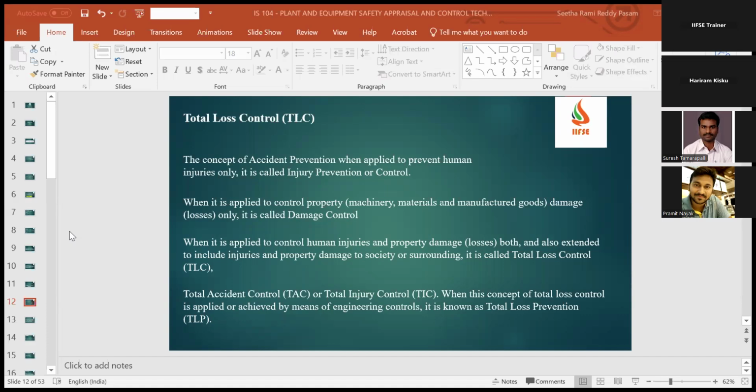then I'll go for engineering controls. I can put sensors in case of any leakage, detection systems, and auto controls. I can even automate the process, with no human intervention in my process, completely a DCS control, digital control system. Then I'll have emergency alarm or shutdown systems.